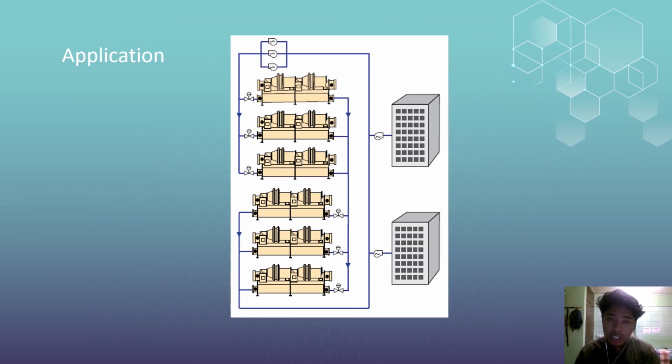A large difference in temperature can help reduce flow and required pipe size. In general, the larger the system, the higher the temperature difference should be. Larger systems are almost always water cooled, so both chilled water and condenser water pipe will have to be filled with water.